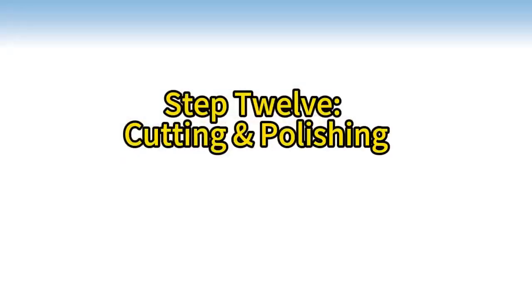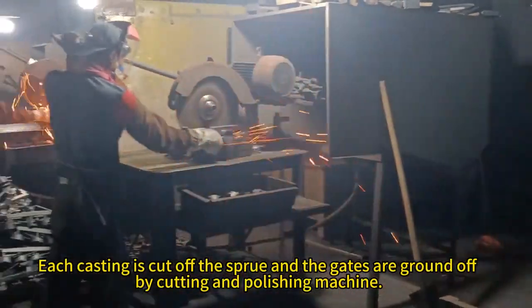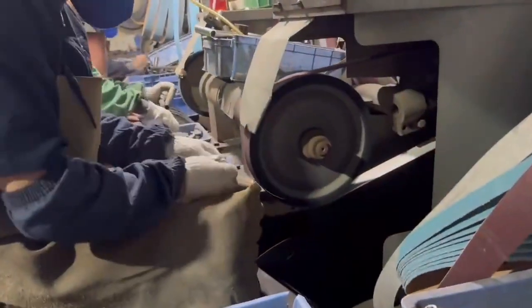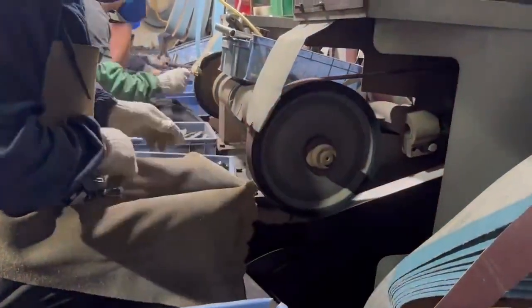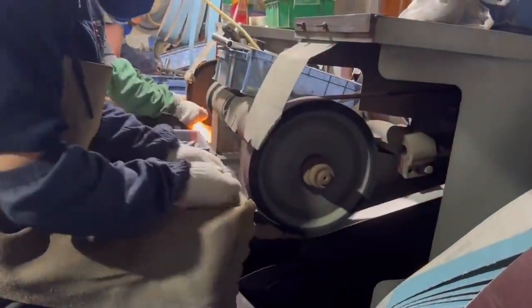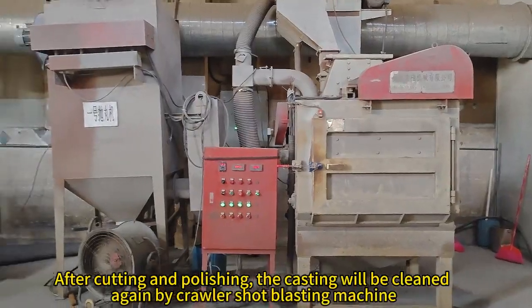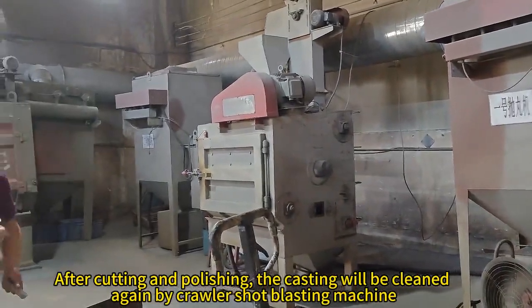Step 12. Cutting and polishing. Each casting is cut off the sprue and the gates are ground off by cutting and polishing machine. Step 13. Cleaning by crawler shot blasting machine. After cutting and polishing, the castings will be cleaned again by crawler shot blasting machine.